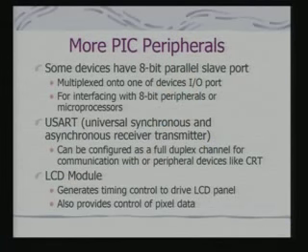In fact, in the example that I had already shown you, the clock, that means a real time clock, you can implement by picking up a simple PIC, interfacing an LCD module, putting in a crystal, and obviously writing appropriate software and loading it onto the PIC. You really do not need any other components.